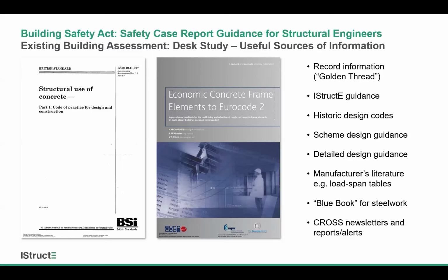It might include specifications, testing data from construction, such as concrete cube strengths. Ideally, although we haven't had any of these really, calculations, or more likely you might find design philosophy statements where at least you have some clarity as to what the basis of the original design was. Things like ground investigation reports that might highlight any particular concerns around aggressive ground or settlement, etc. And then fire strategy and compartmentation drawings, which will obviously be relevant from a structural fire resistance perspective.